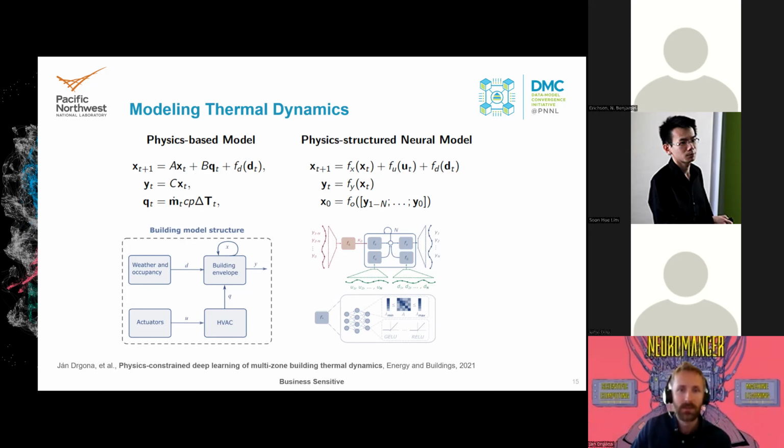So this is the basic structured recurrent neural net that gives you this recurrent update on the state trajectories that represent the latent temperatures in the building. And we know the dynamics is dissipative. That's why we put these eigenvalue constraints to be strictly stable within the unit circle. So it's always contracting and getting to the thermal equilibria. We know that our HVAC system has bounded input, bounded output properties, and we know what the physical bounds are. So we can just clamp the output of this neural network to be within these physical constraints. And we train only a smaller number of parameters than we would need with fully connected neural networks, because now our solution space is fairly limited.